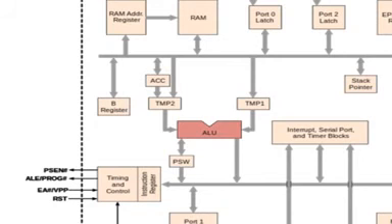That means A is the destination and B is the source. Whatever values are there in A and B, both will be added by the 8051, and in the end the result will always be stored in the destination register. Now in this instruction ADD A, B, the destination is A. So the result will be stored in the A register only.